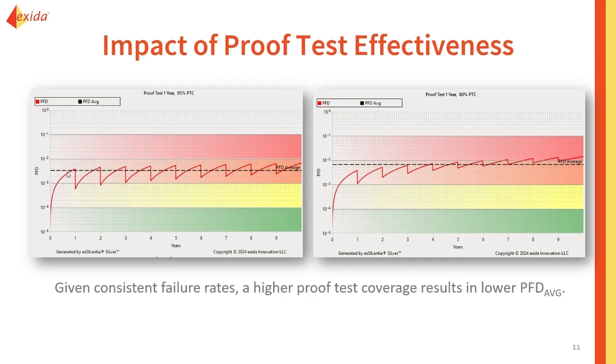It's always nice to revert back to these PFD charts in order to see exactly how the parameters that you're inputting affect your results. If you have an online test with no alternative protection, you're going to see that although the PFD ultimately dips, during the time that test is being performed, your PFD is 1, meaning that if you have a hazardous scenario occur, your SIF won't be able to bring the process back to the safe state.